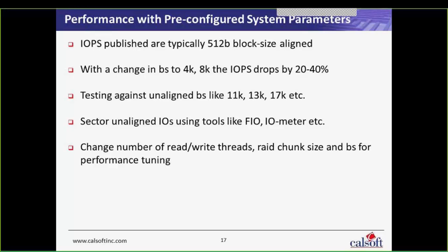We can also have the garbage collection engine kick in during the performance run and see what the performance is at that point in time. So these are all pre-configured or changed parameters that we can run through while taking performance to see how flash behaves in extreme conditions like disk fill conditions, which the flash vendor normally doesn't publish in their results or PRDs. So, moving on to the next slide.